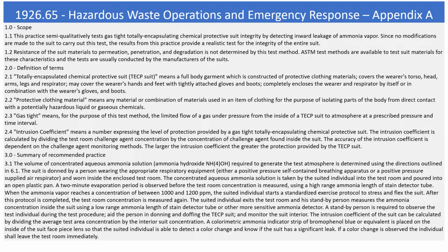2.4. Intrusion coefficient means a number expressing the level of protection provided by a gas-tight totally encapsulating chemical protective suit. The intrusion coefficient is calculated by dividing the test room challenge agent concentration by the concentration of challenge agent found inside the suit. The accuracy of the intrusion coefficient is dependent on the challenge agent monitoring methods. The larger the intrusion coefficient, the greater the protection provided by the TECP suit.